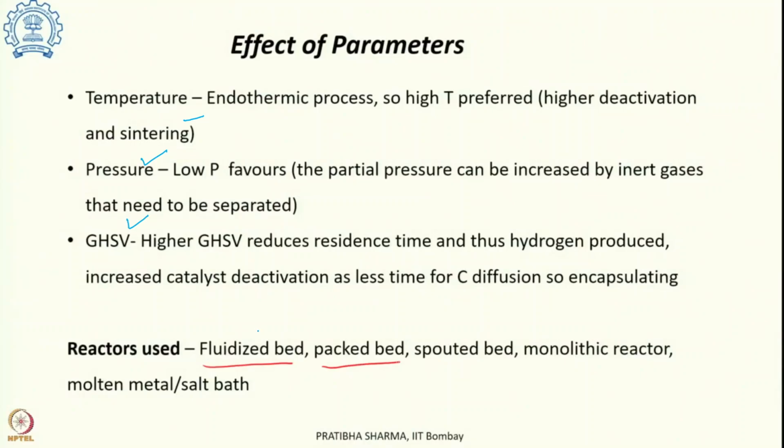When we use the fluidized bed, the heat distribution will be uniform, and the catalyst active site will be open, and when the catalyst active site is open, the reaction rate will be high. For the packed bed reactions, the catalyst active sites will be packed, so the active sites will be very few and the reaction rate will also be less. That's why we will always prefer the fluidized bed.